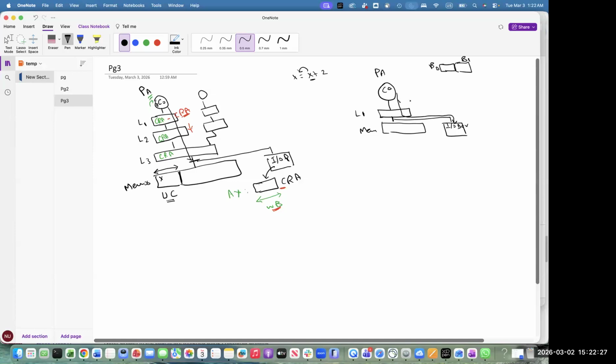You send the second byte, then the third byte, and then the fourth byte. Now the problem is that every time you perform a write on the system bus, you are paying the latency, right? And the unit of sending data on the system bus is a cache line, right?